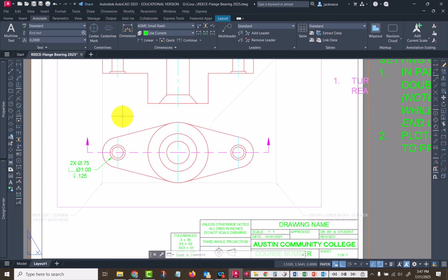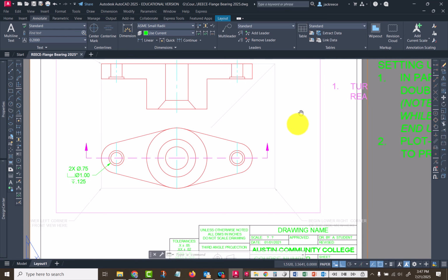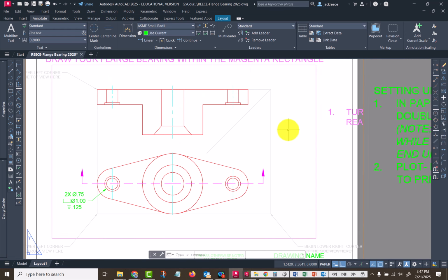Except in this case, you're going to use a lowercase w to put in the countersink symbol. Okay. And then, of course, a degree for the degree symbol. The textbook's pretty clear on working through those things. So you'll get those dimensions.